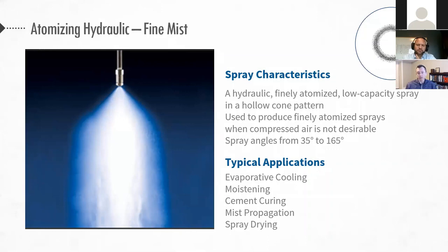Yeah, you can imagine after droplets, especially if they're small, after they leave the nozzle, even if they form into a hollow cone, they're going to start to disperse and move around just due to the air turbulence, either from the nozzle, from the process gas, or themselves just mixing up the surrounding environment, right? And so you typically see downstream of the nozzle more of a full cone or filled-in pattern, even if it is a hollow cone fine spray. But these nozzles are designed to operate at much higher pressures to allow you to use the energy within that liquid to generate smaller droplets.